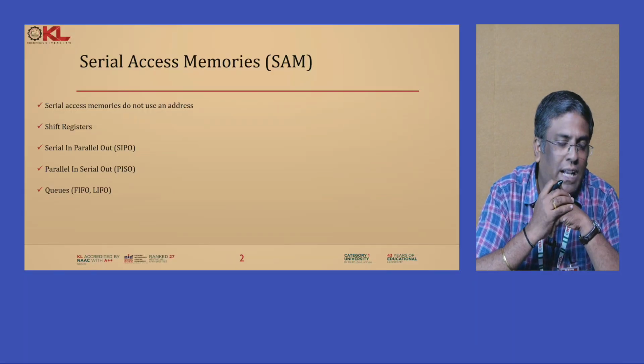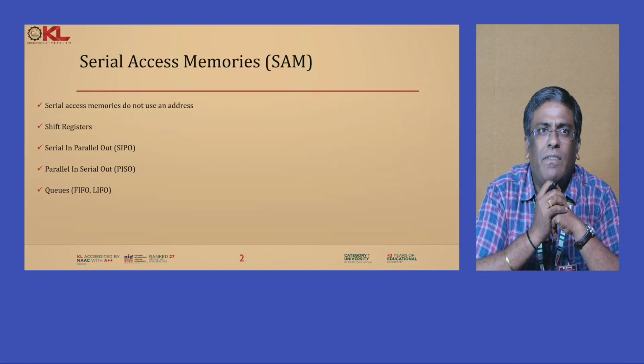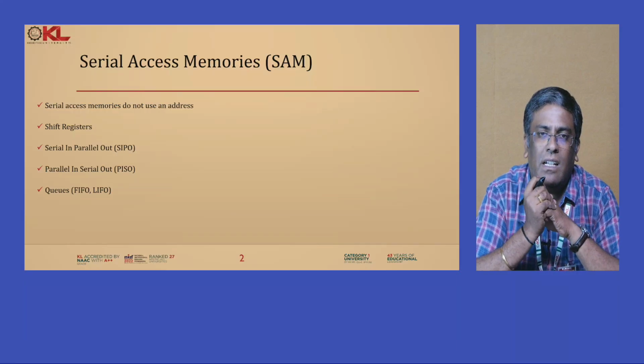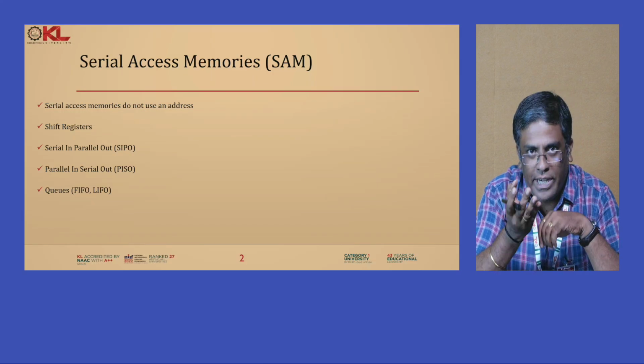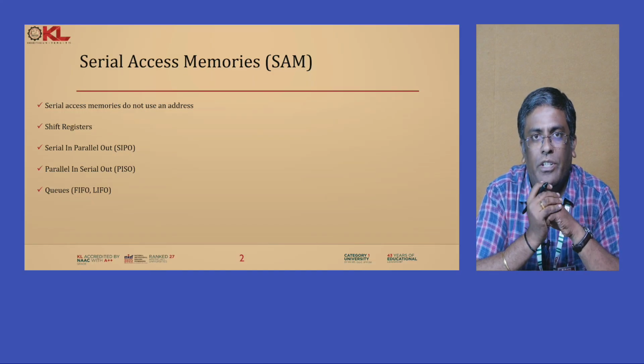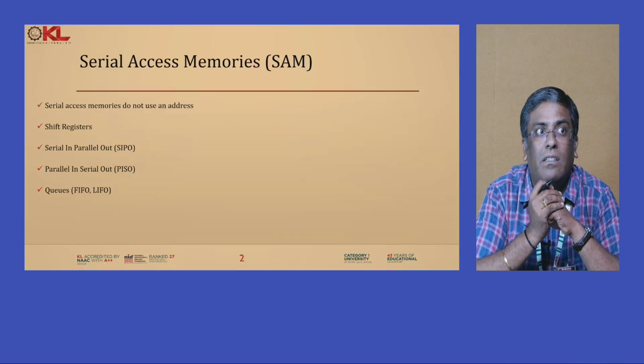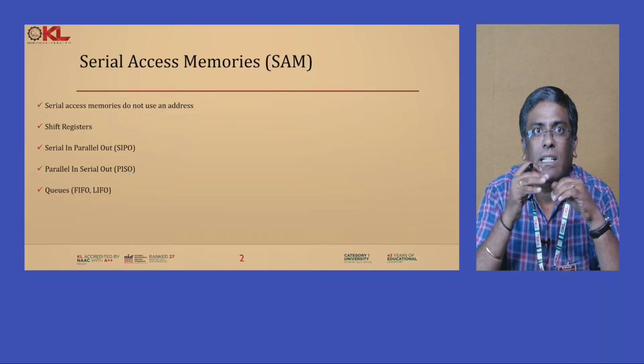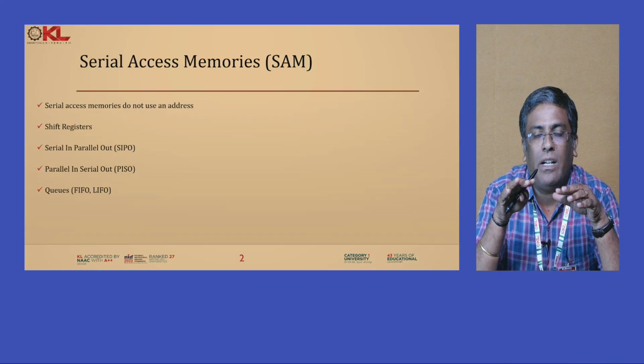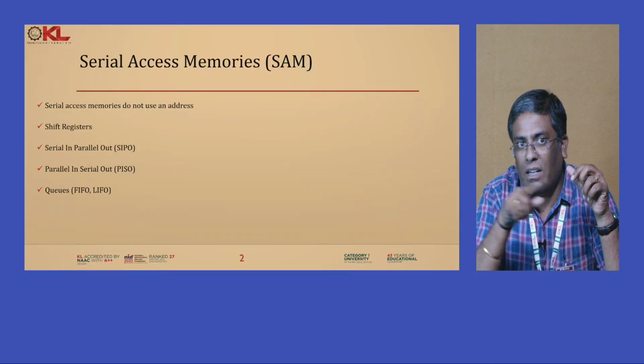Of course here also we will have a row and column structure, but in the SRAM and DRAM we make use of the bit line and word line to access your row and column. Same way in the DRAM we make use of the bit line and word line, and in the ROM architecture we make use of Q0 to Qn minus 1 for read and write operation, acting as a column selector, and for row selectors we have the address lines available.